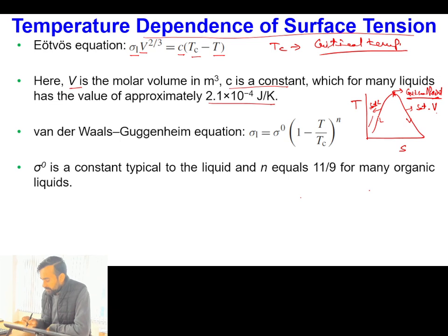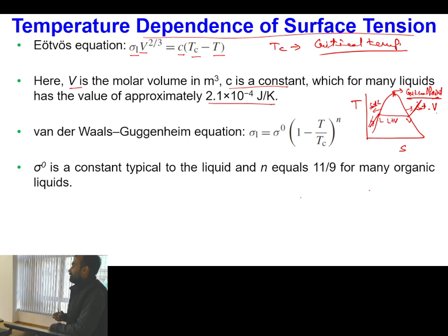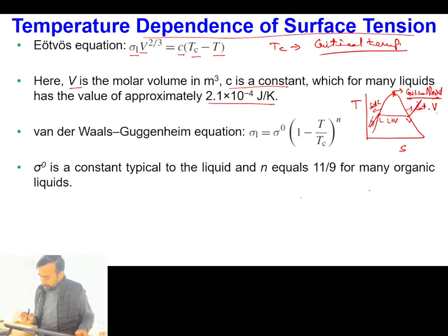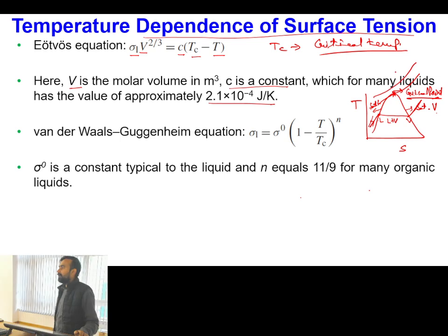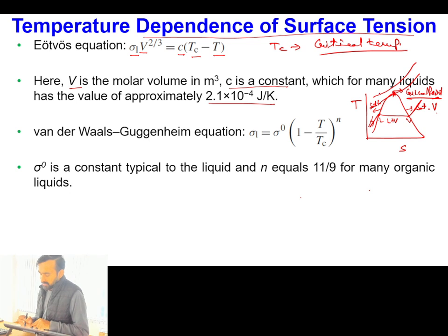Can you tell me how a constant pressure line moves over here? This is how the constant pressure line is. Below this point I have subcooled liquid, here I have saturated liquid, in between the dome I have a mixture of liquid plus vapor, and above this point I have superheated vapor. But if you consider a pressure line which is moving through this critical point or above the critical point, what will be happening? For these pressure lines, can you separately define where is liquid, where is vapor?